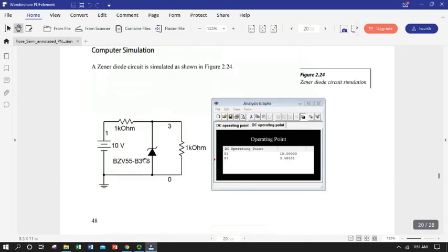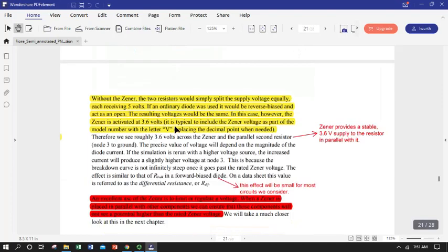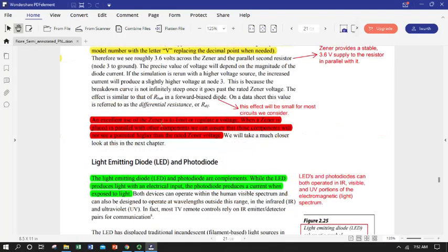And as a note, Zeners are one of the semiconductor components that you have available to use in your simulation package with TINA. So you can go ahead and practice using Zeners in a TINA circuit, as well as using them in your proto board with your kit if you are doing a live lab or a physical lab. Typical values for Zeners, 3.6 is one that you'll frequently see. A 9 is something you'll encounter, and they come in a large range of voltages.